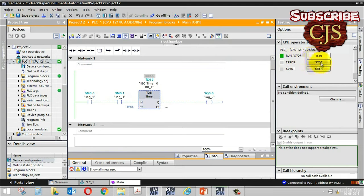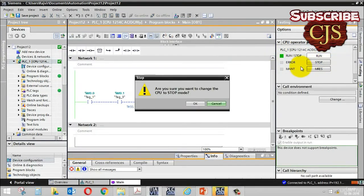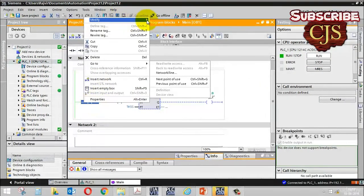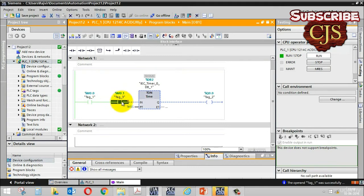Now this is PLC run mode. If you want to stop your PLC, you can do it from here. Now PLC is at stop mode. Again, this is at run mode. So again, if I turn it on, because it's a series logic, this will start my timer, and your output will be on in 5 seconds. This is how you can simulate your PLC logics in Siemens TIA.